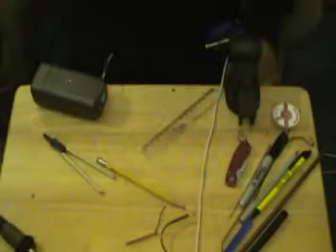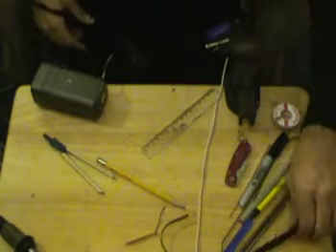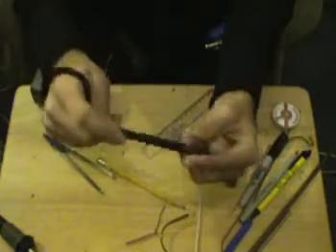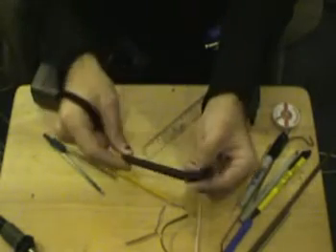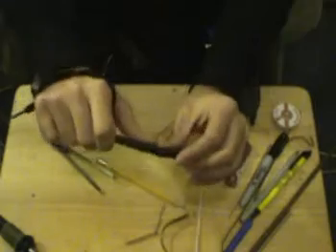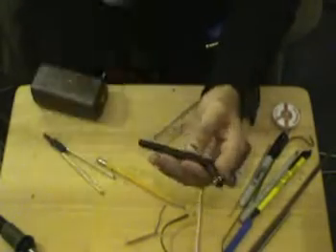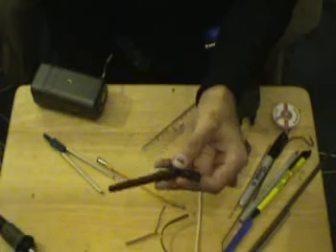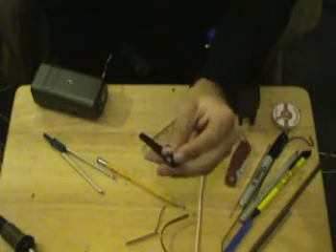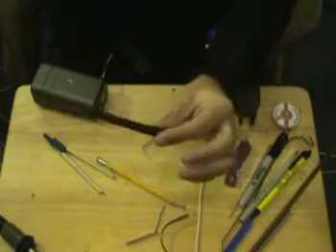Before we begin, I want to analyze a couple of commonly found dipole antennas that we have in our 2.4 gigahertz products. The first thing I want to show is, we've all seen these little default antennas that come with your router. These are called rubber duck antennas. It's got a standard reverse polarity SMA connector, and inside of this is a typical dipole.